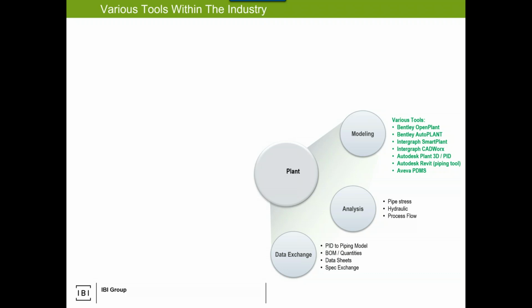In the world of buildings, I dream. Let me have my model, scan my model, do a fundamental first pass of my technical specs. In the world of plant, specs come first, laying the premise. And I think I described in week 1, copper can only go from a small size to a large size. So if it's, I don't know, 1/4 inch up to, I don't know, 3 inch. If I want to come in and make a 10-inch copper pipe or a 50-inch copper pipe, system's going to say no. In the same breath, I will never make a 1/4 inch reinforced concrete pipe. It will never, ever happen. It's just nuts. So that happens.